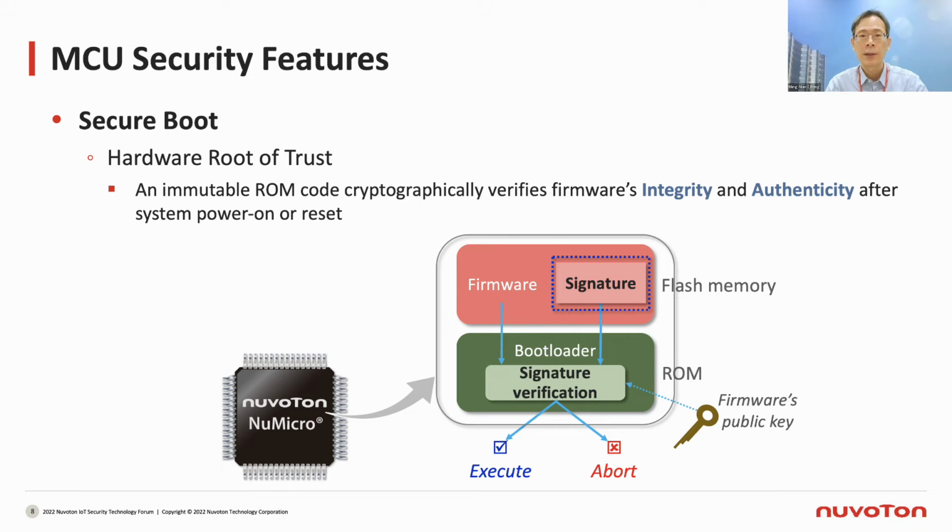According to the digital signature algorithm, if the firmware content is not modified and is signed with the correct firmware private key, the verification result should be correct, and the secure bootloader will jump to the firmware for execution.